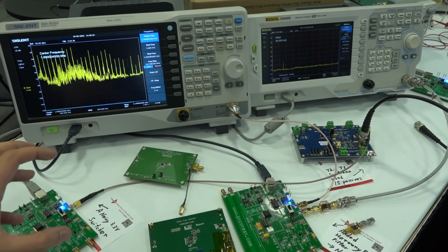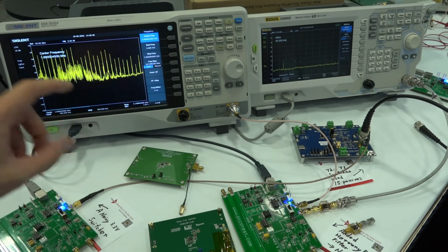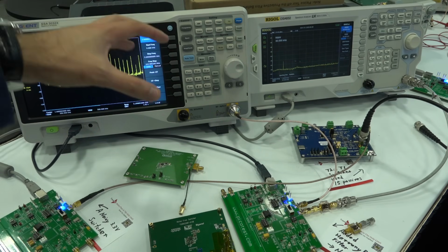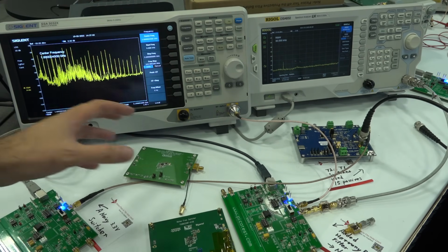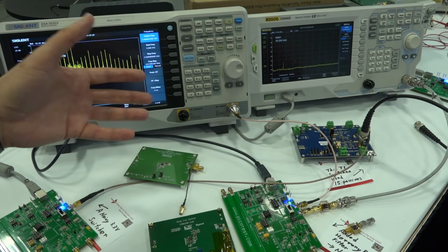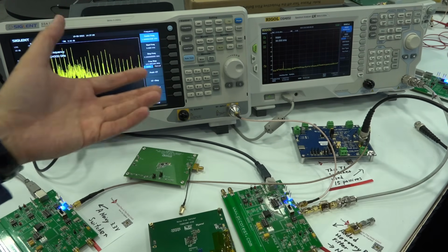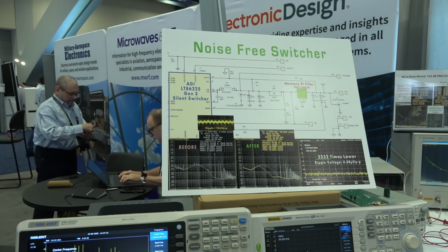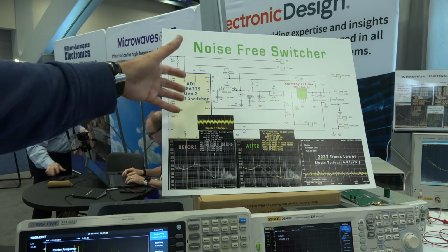Now, whenever you want to feed a sensitive system with a dirty power like this, you are going to have some of these signals up-converted to your carrier. It's impossible to feed a very sensitive PLL or a sensitive synthesizer with a dirty clock and not see the effect of that. So the solution is what? The solution is obviously to filter your DC-DC converter in some way, and there's an actual example of where their product sits. So here we have the ADI's Gen 3 silent switcher.